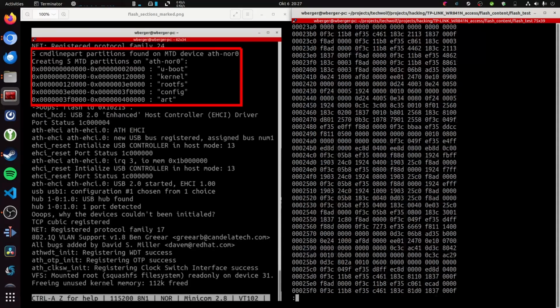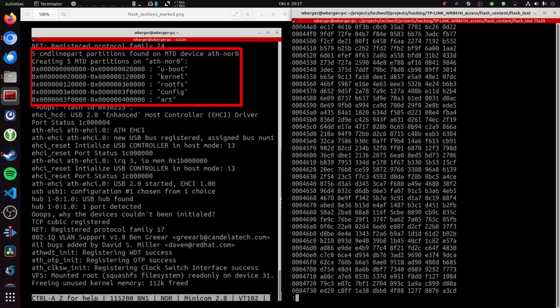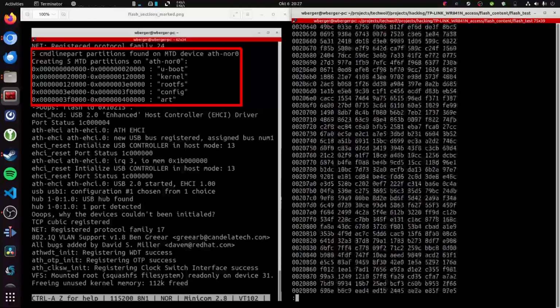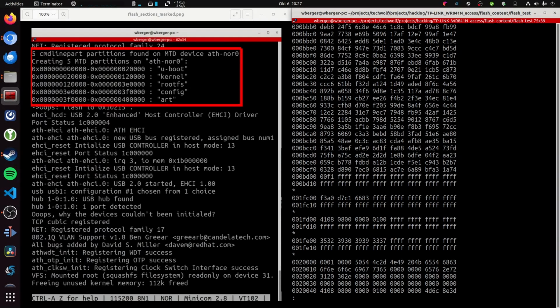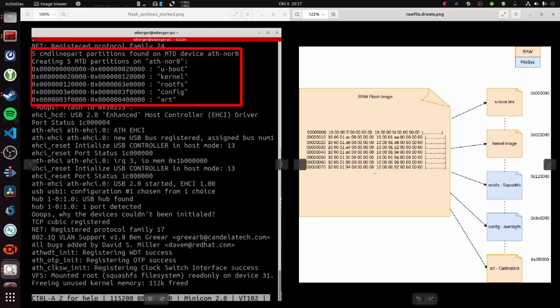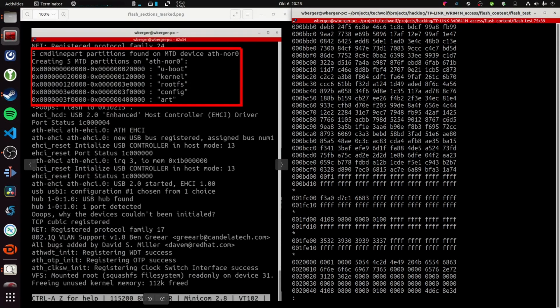Let's scroll down. Maybe a little bit faster. Yeah, and here it was. You see, okay, after a certain offset, there are lines with a star. That means there is the same bit pattern for that many lines as long as it doesn't change. So here we have a change, so this is the reason why this is shown. And this means, okay, we reserve space as an offset for, let's say, U-boot, but we don't have to fill it completely. So F normally means, hey, this is the erased flash. And at 20,000, we see the kernel image starts.